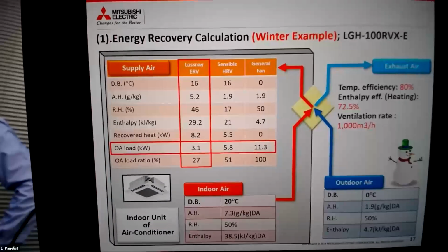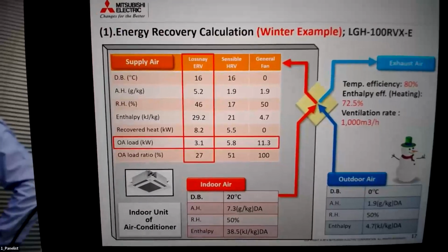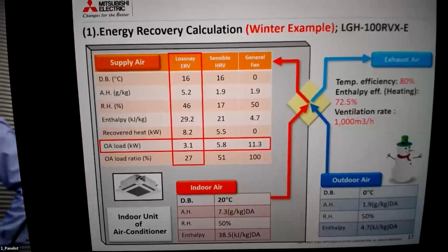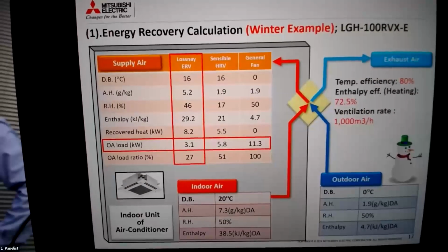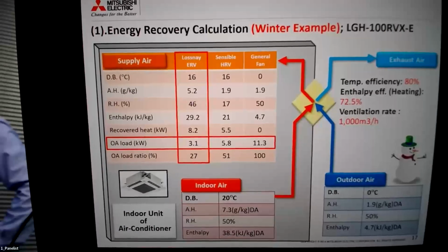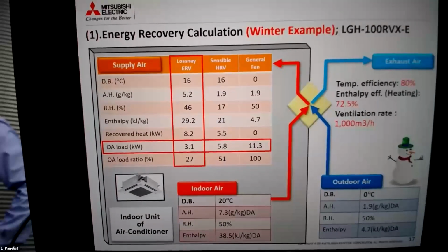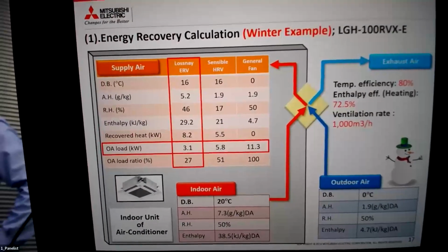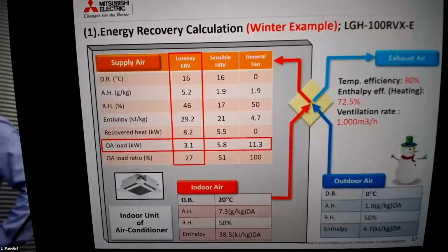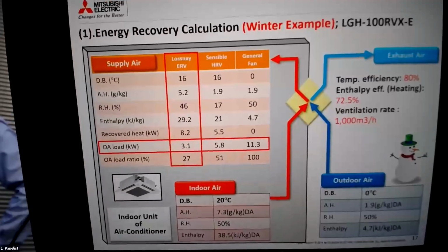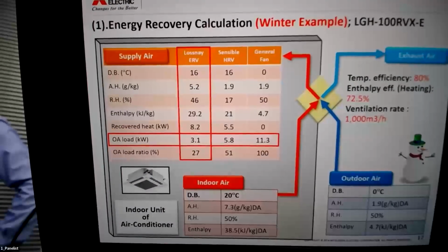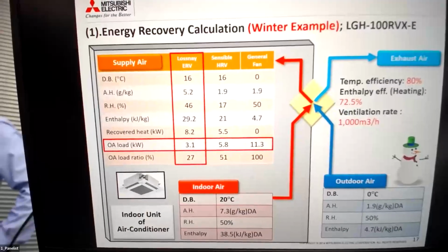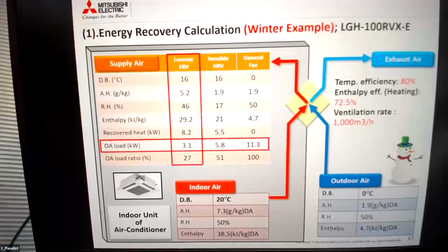Say there is a one-to-one relationship and you transfer 10% of ammonia back. Then maybe you can increase your ventilation rate by 10%, you will reduce your concentration, and this transfer will be dealt with by keeping the level of ammonia lower in the first place. So when it's transferred back, it should not contribute significantly to the exposure in a space. I need to make this calculation, whether it is a one-to-one transfer, but I just give you an example of how it can be tackled. Thank you very much.